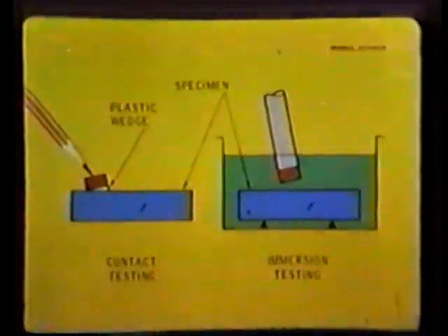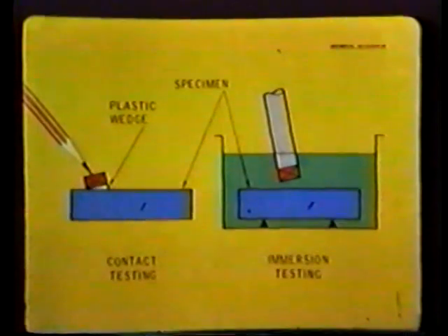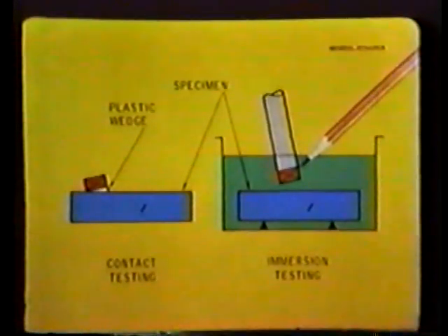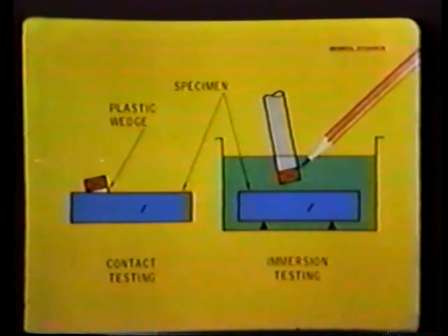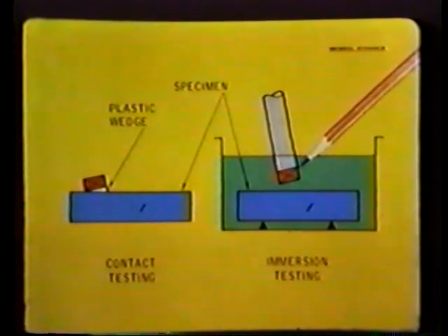In contact testing, an angle beam transducer is used to change the direction of wave propagation. In immersion testing, the transducer is simply angulated. Through refraction, mode conversion, the direction of wave propagation is altered to locate discontinuities which might otherwise go undetected.